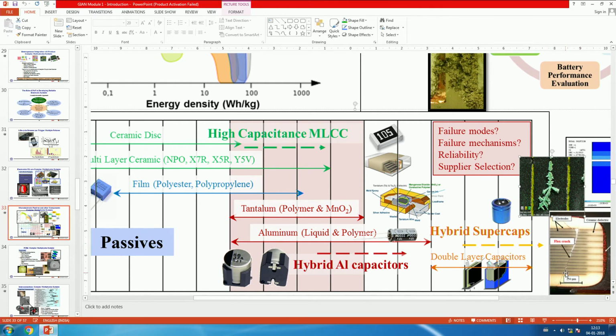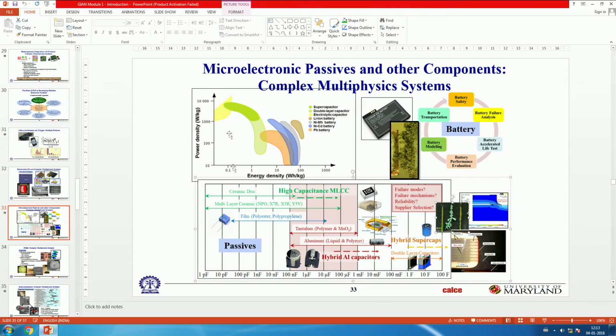And the reason those grow is because these ceramic capacitors get micro cracks in them. Then moisture gets in through the micro cracks. That's how the moisture is available. And then the voltage gradient between the plates in the presence of moisture makes those dendrites grow. So, bottom line, lots of physics of failure challenges in passives also. Okay, power supplies, passives. Let's go to the next one.